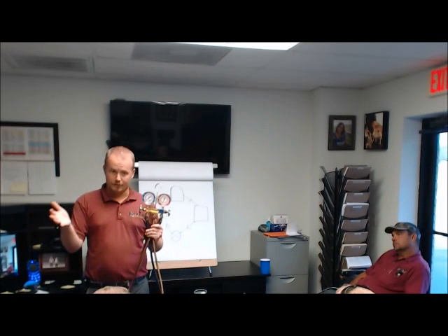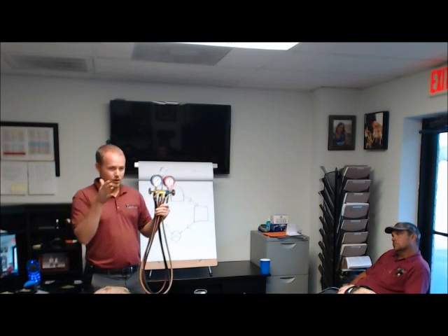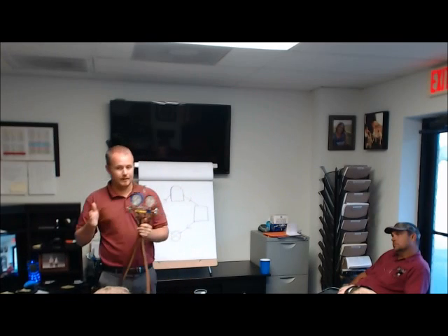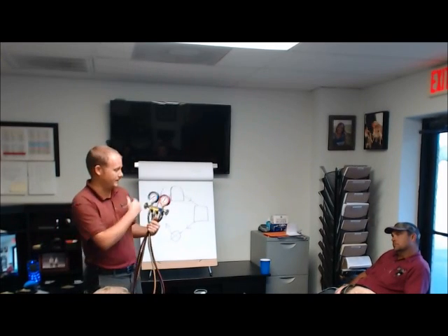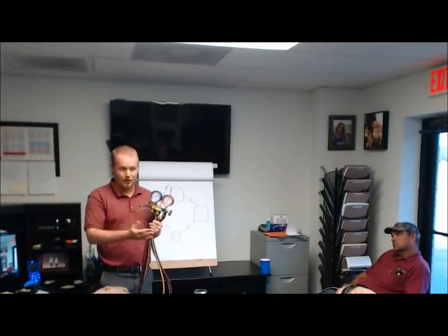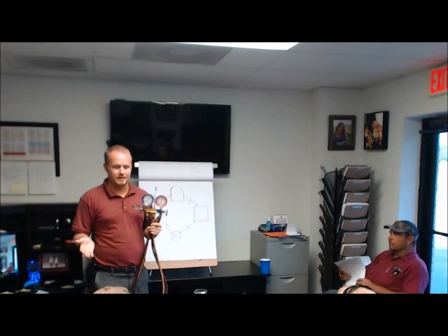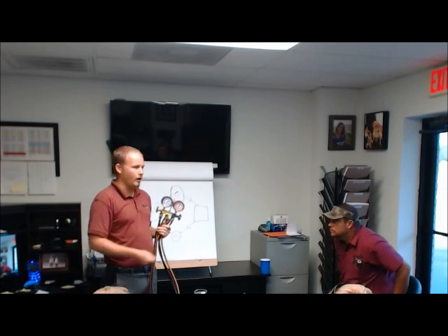It's a mixture of the two. It will have certain pressure characteristics at certain temperatures. So when you walk up to a system and it's off, that's what we call static pressure, meaning that you don't have anything affecting motion of the refrigerant within the system. So you hook up to a system that's off, you call that static pressure.